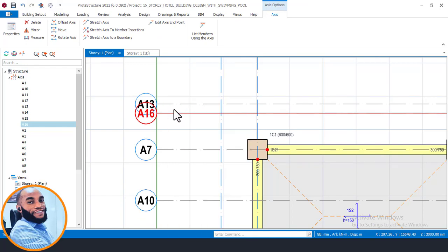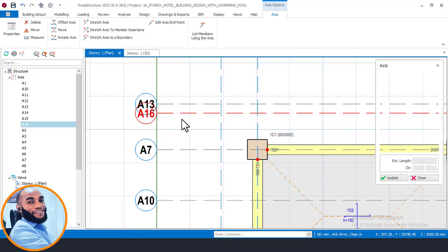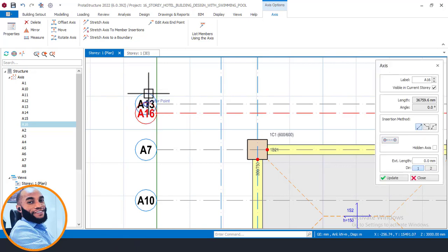We can choose to turn this grid line into a hidden grid line. I'll turn my cantilever grid line, which is the edge of the cantilever, into a hidden grid line. The reason for that is that we will not confuse it with the other lines that are trying to complete with a name. So I know that all my hidden lines are the cantilever edges. So right now come here and say hidden, and I'll remove these bulbs here. I'll take it off and take it off again, and I'll come here and click.